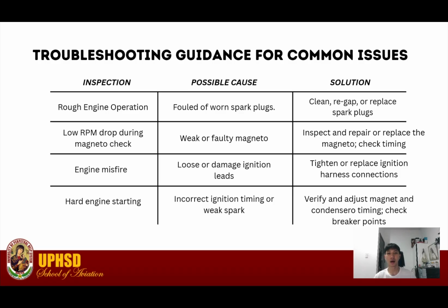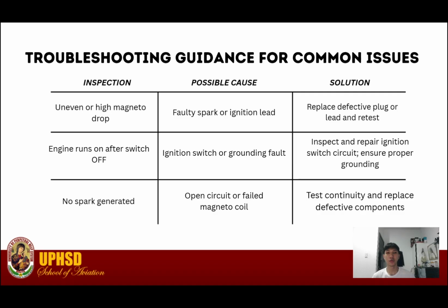Lastly, hard engine starting is often due to incorrect ignition timing or weak spark. To fix this, we must verify and adjust magneto and condenser timing, and check the breaker points. Let's continue with more troubleshooting procedures related to ignition system.